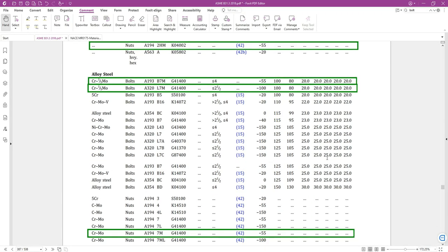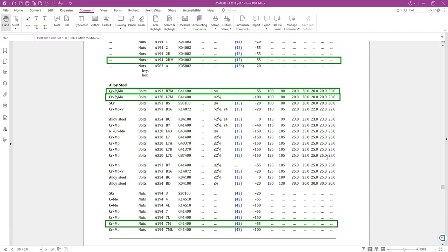Here I have an important point. Based on the information received from other process departments, the minimum design temperature condition only occurs during depressurizing scenarios, and it may happen less than 10 times during the whole 20 years of the design life. Each depressurizing duration is less than 1 hour, so as our pressure vessel is not in direct contact with low temperature process gas, but it is always in contact with H₂S containing sour gas, I prefer to prioritize NACE requirements instead of low temperature conditions.